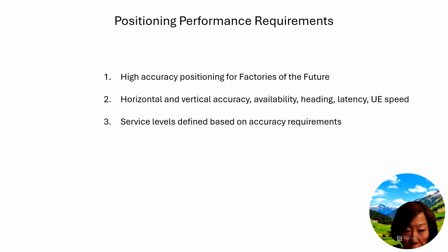For applications requiring relative positioning, 5G supports device-to-device D2D positioning techniques. These might involve direct ranging between devices using side-link communications, or cooperative positioning where devices share their location information. The system also supports techniques like simultaneous localization and mapping, SLAM, which can be particularly useful for applications like autonomous vehicles in industrial environments.